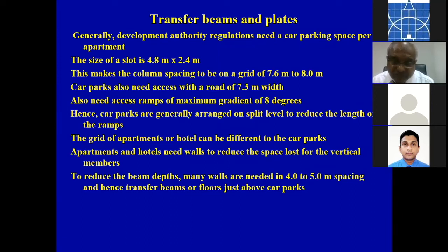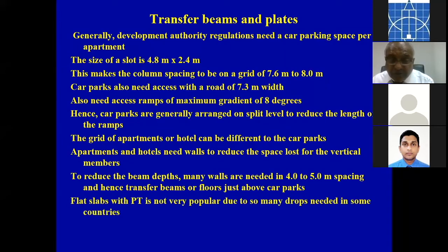Within that, it's hollow. So that's another attractive option. Easier to cast as well, because we can cast the bottom slab first with starter bars for beams, and then we cast beams and the top slab together, and we sacrifice the formwork that we used to cast the voids. So that formwork will be there forever, and we don't see it, so we are not worried. And you can use old timber to make the formwork.